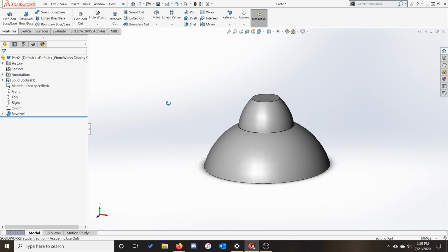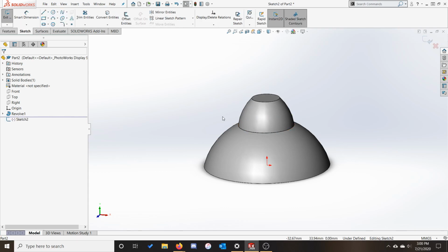Now that we have our base shape down, let's carve out a little indent on the shade itself. Since this cut is going to be using the same central axis, we could have done it as part of the initial Revolve. However, doing so would limit our editing options, making it so that it would be difficult to remove the carving for future iterations if we ever wanted to have a smooth version.